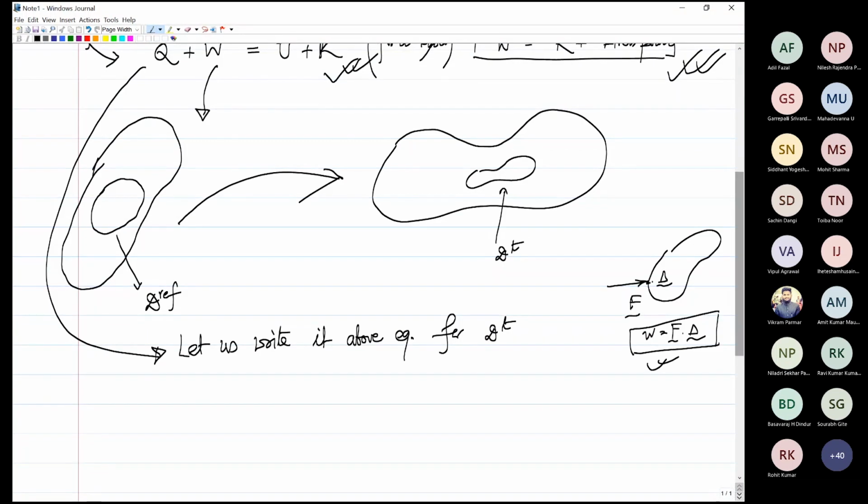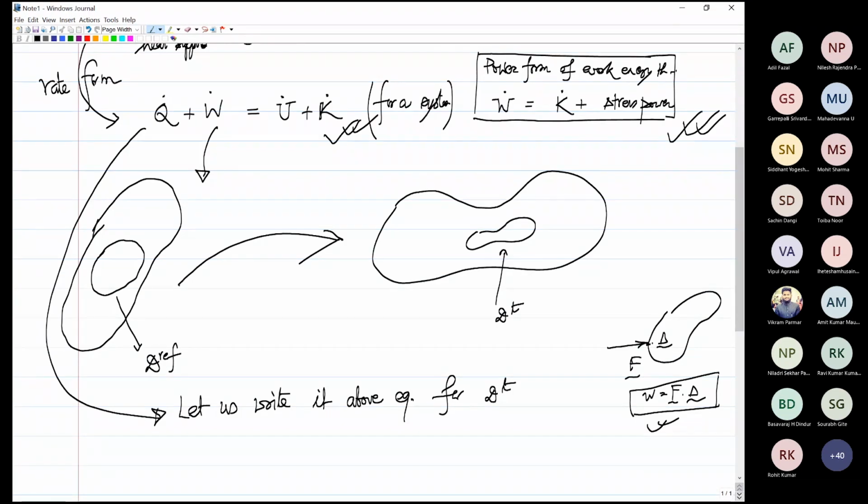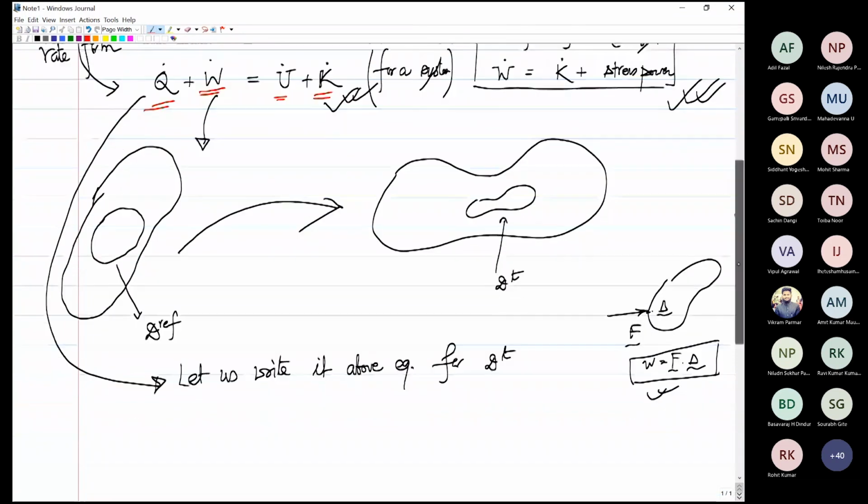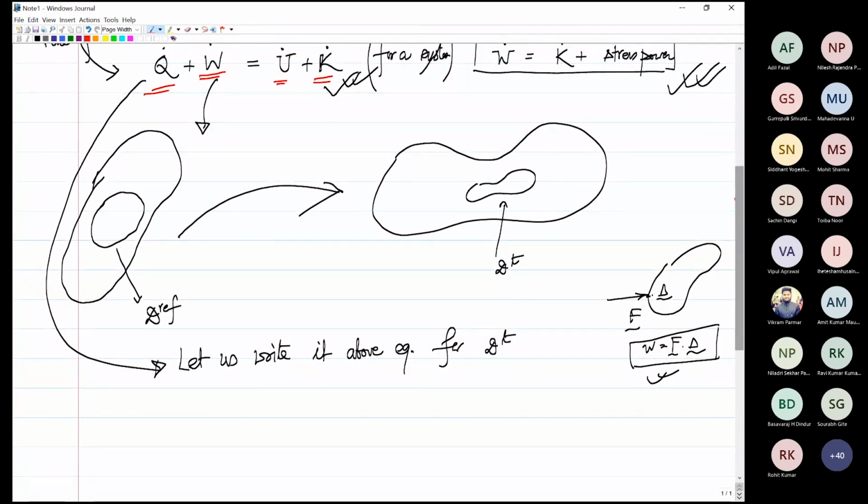With that in mind, let us try to write this for each of the terms here. You have 4 terms. Let's first write W dot. W dot is the mechanical work done by external forces. It has to be by external forces, because you have a system and Q being supplied externally from the external environment and W being done from the external environment.